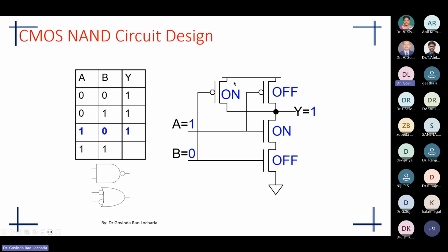And in the upper part of the circuit, what I'm showing here is the pull-up. This parallel combination of these 2 MOSFETs is the pull-up segment, or pull-up network. So here this helps the output to source 1. When the pull-up source is connected to the VDD, then the output node will be connected to VDD through this pull-up segment. By that time, the pull-down segment path will be open circuited.